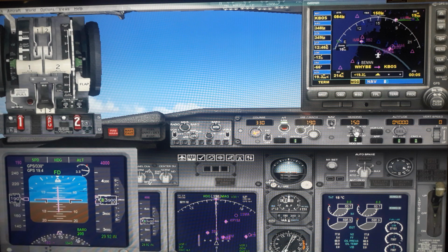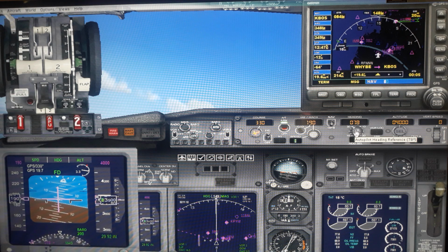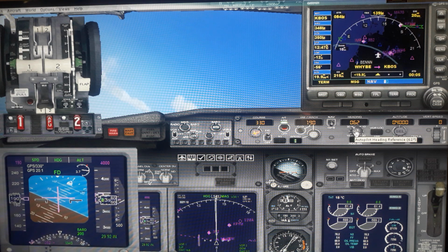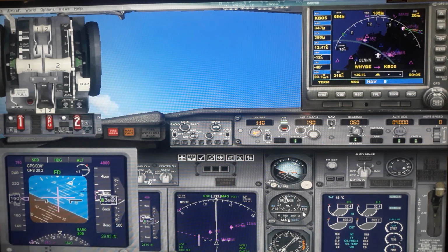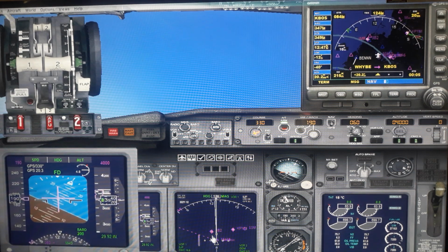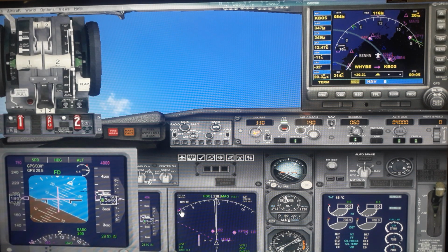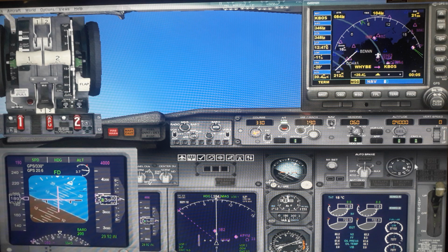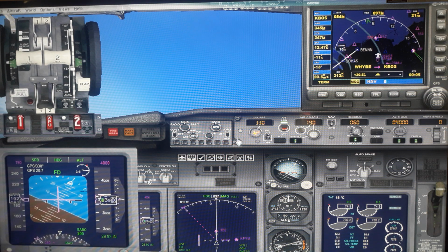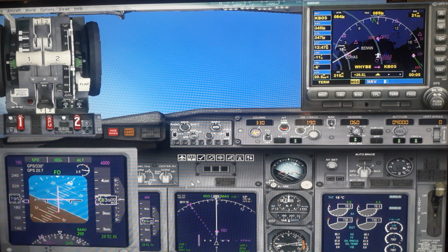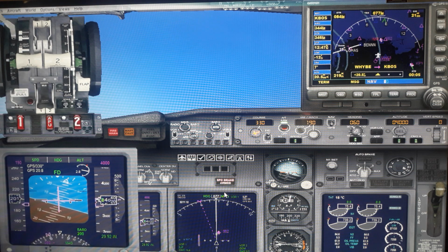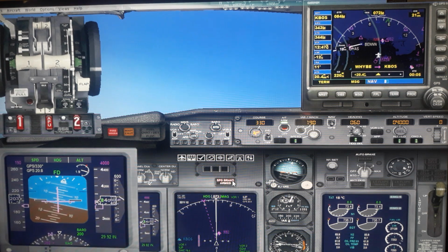Okay, now I will turn this left to 60. The plane is turning left. You can see this is the 60. Now I'll keep scanning what other things I need to do. Course is set, radio is set. I need to arm the speed brake. You arm the speed brake. You see that's the one which will come up on top of the wing.